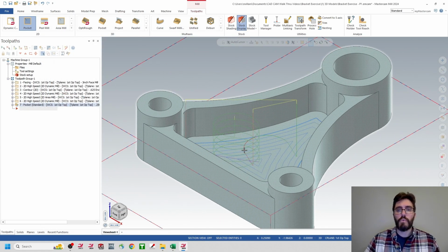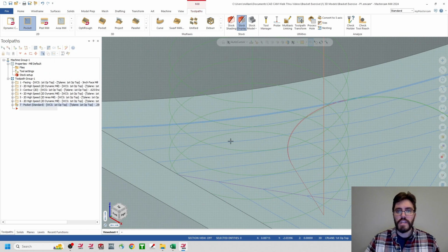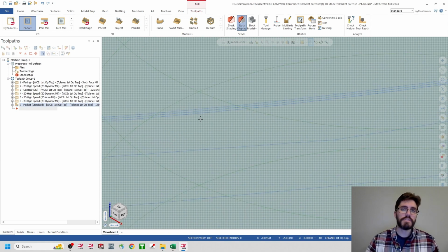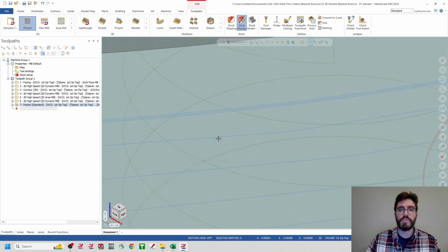And this is, again, why I love this toolpath so much. You can see these nice equal offsets for the toolpath as it's cutting. And in that finishing selection that we made, we were able to control how much the tool was going to step over for each one of those finishing passes. So we said that we were going to do 2 finishing passes. That's going to be the 2.5 thousandths there and there. And then this last pass over there was going to be the offset from this value right there.